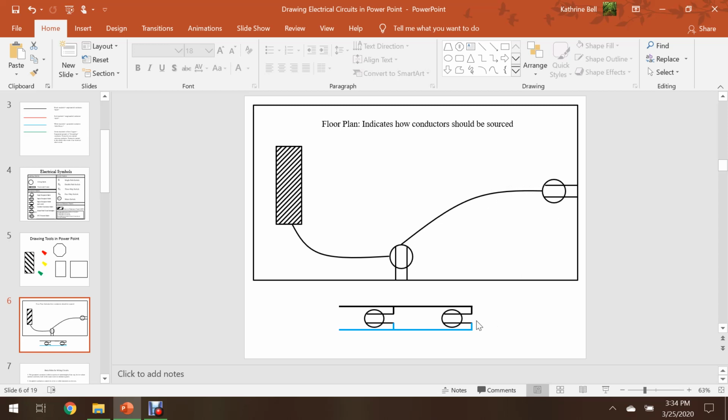Down below we have a ladder diagram or ladder logic. Looking at the ladder logic, we've got a black line. This black line represents the ungrounded conductor. This is one 120 volt phase coming from a circuit breaker inside the service entrance panel. You'll notice that it runs uninterrupted.